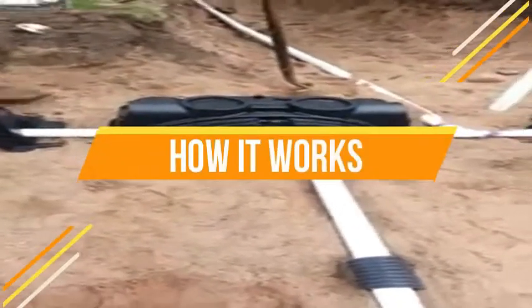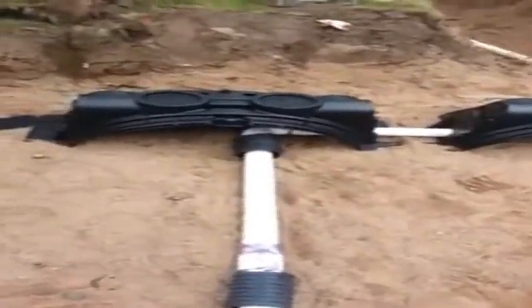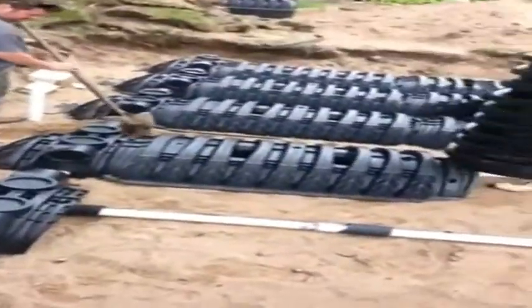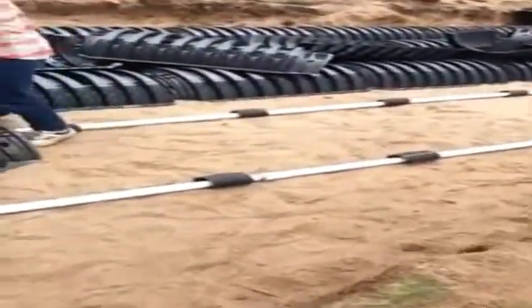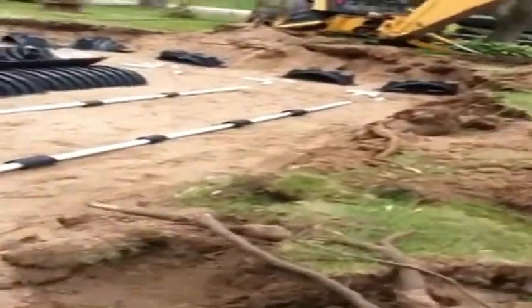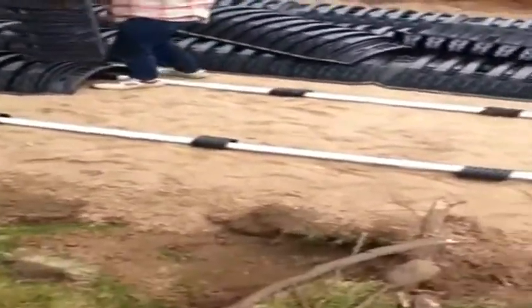How it works. A septic tank works by allowing waste to separate into 3 layers: solid, effluent, and scum. The solid settles to the bottom, where microorganisms decompose it. The middle layer of effluent exits the tank and travels through underground perforated pipes into the drainage field.